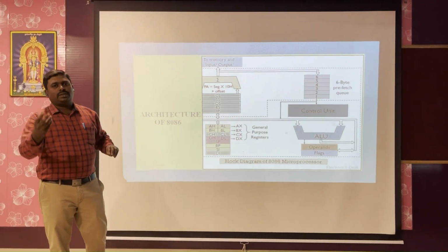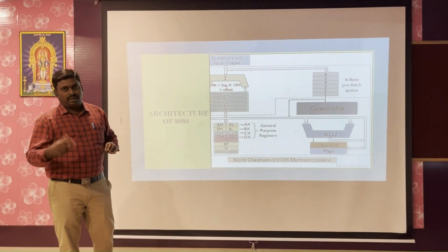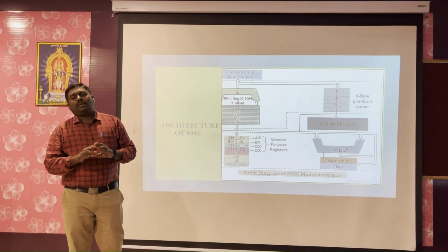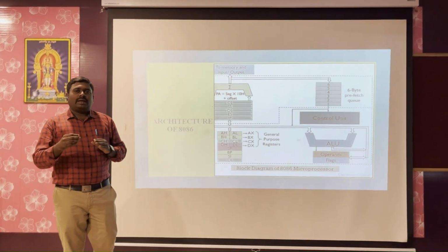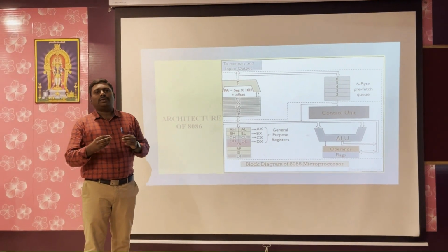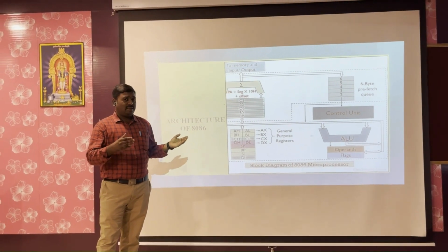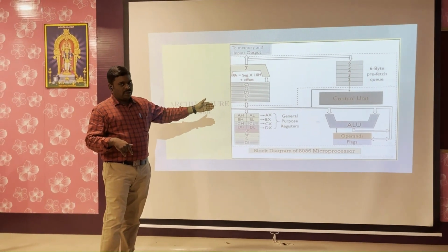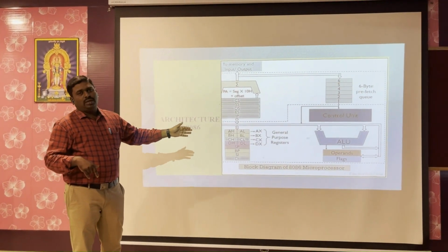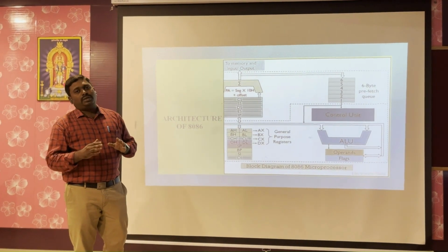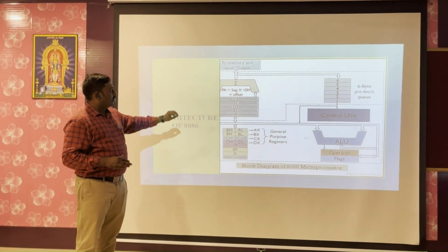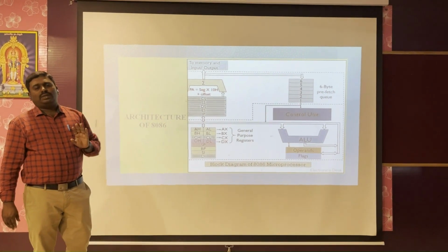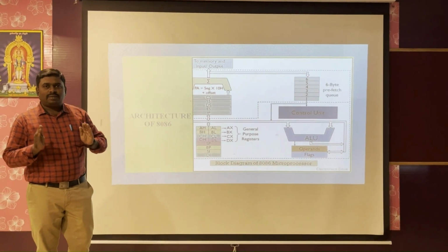From this operation, some flags are generated for getting the output. If two bits of data are added, a carry is generated by adding these two bits, so the carry flag will be set. Let us see the flag registers in the following slide. Before that, after performing the operation, the output goes to the flag registers. After the operations are executed, the data is again passed through the segment registers and moves to the other devices. So the processor has segment registers.